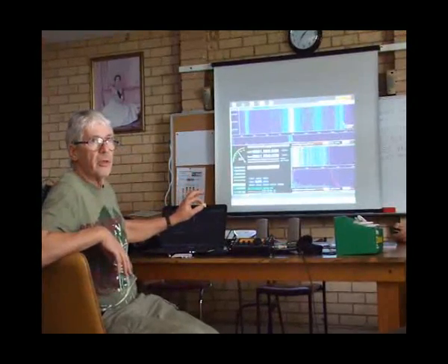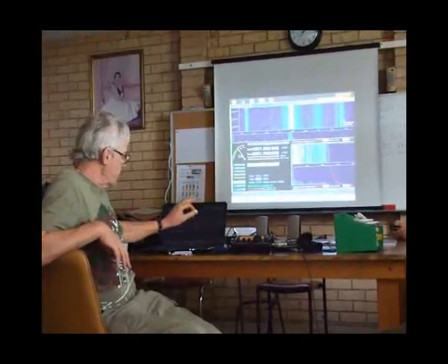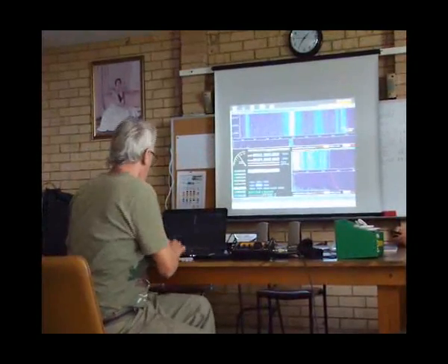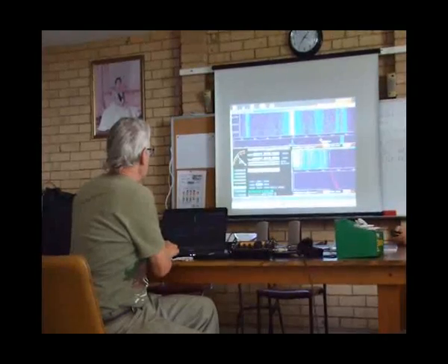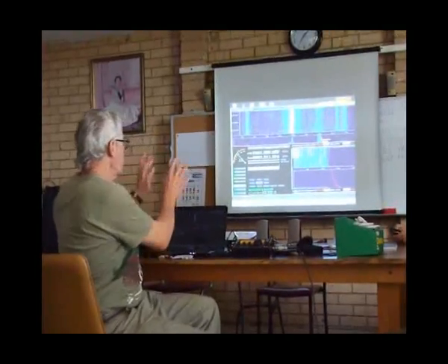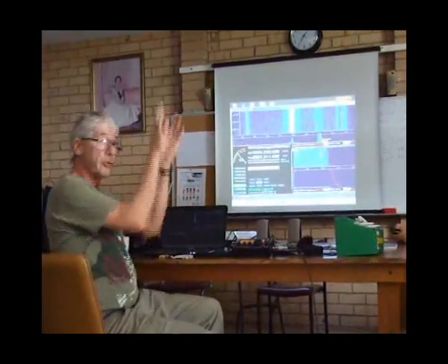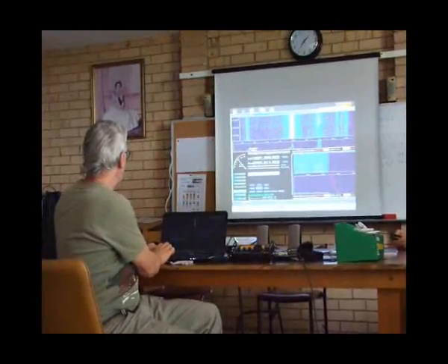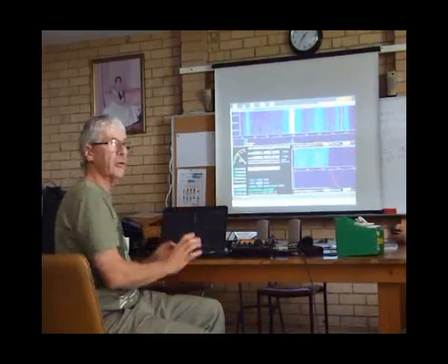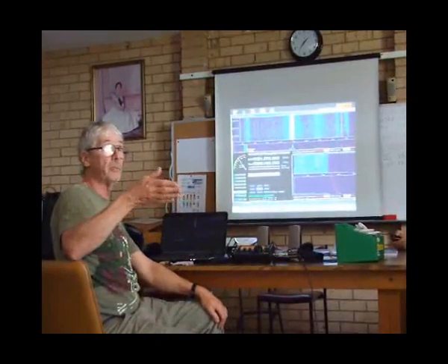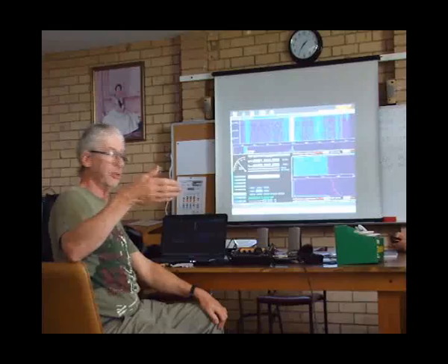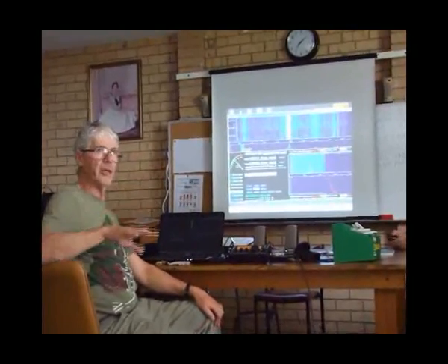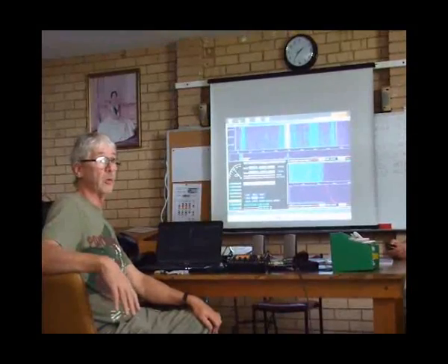An advantage of implementing CAT control is that you can put a cursor on the spectrum and click there, and if you've got CAT control enabled, it'll just jump to that signal. You just say, oh, there's the signal over there, I want that, bing, and you're on it. It's like how the P3 pan adapter with the Elecraft knows what the rig is doing, and they talk to each other. Under those circumstances, it's amazing what a difference it makes.